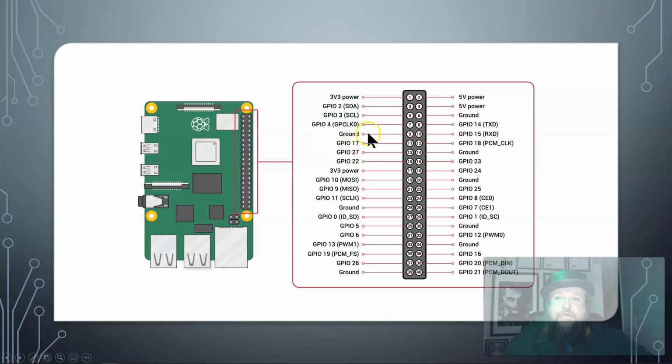but internally within the hardware and everything else, it's referenced and talked about as being the general purpose input and output pin number 17. And so in your code, when you want to indicate, okay, I want to use the GPIO pin 17 a certain way, you're going to use that number 17, importantly, when you're doing work with it. But that's again for the Raspberry Pis.